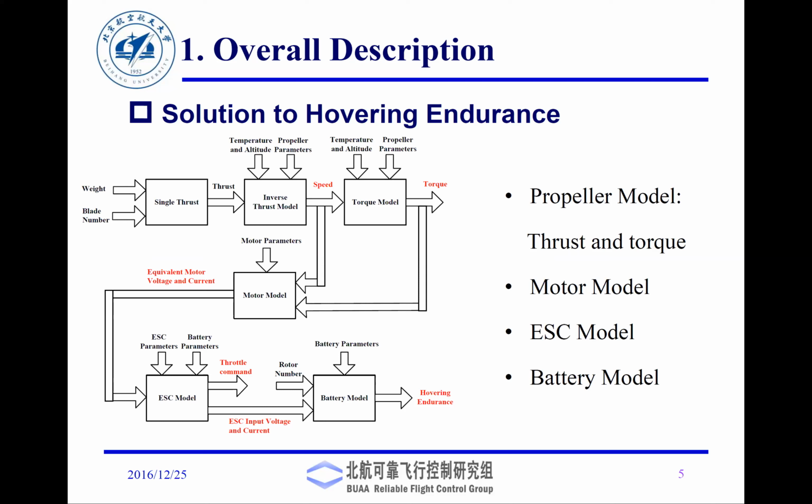Okay, so we are going to look at these individual blocks. We are going to look at the thrust. Then from that thrust calculation, we are going to find out what prop size we need. Then from that prop size, we are going to find out what motor size we need. From that motor size, we are going to look at what type of AC we need. And at the end, we will decide what battery we need.